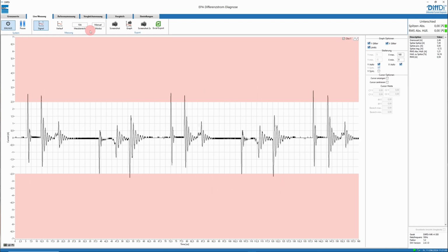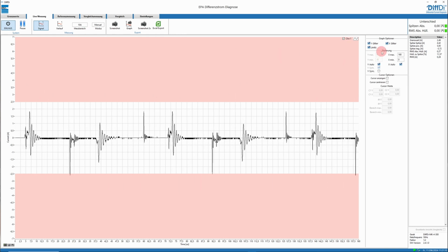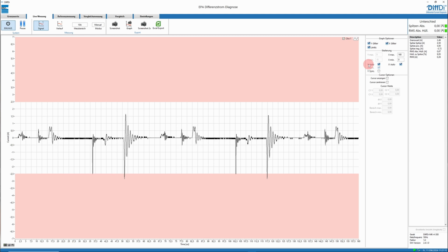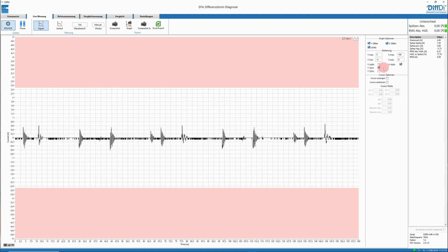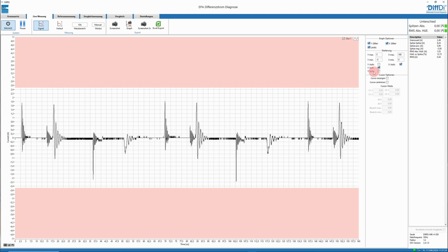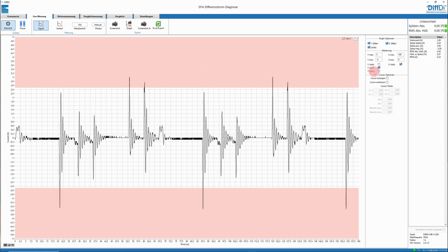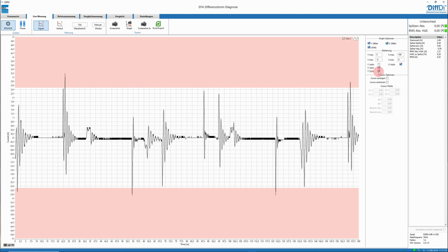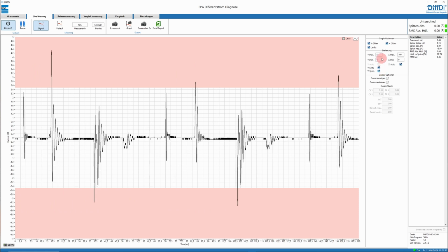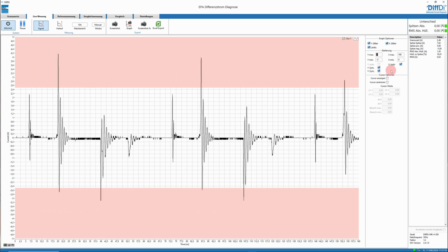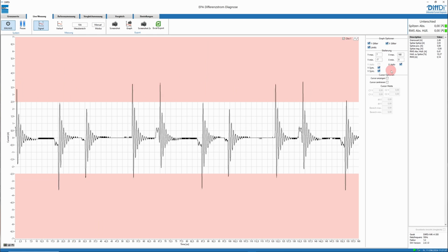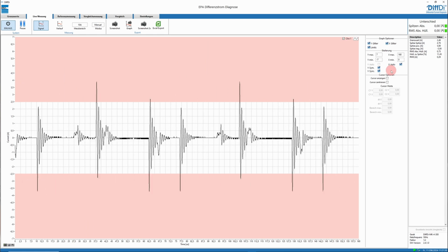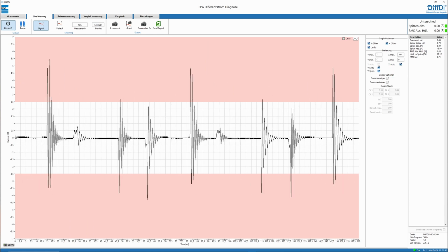The scaling of the 2 axes is normally set to Auto. Manual entry of the scaling is also possible under the graph options and, as in our example, also makes sense. Before entering a value, you should check whether the Y-sync checkbox is ticked. This has the effect that the value entered for Y scaling is transferred directly to the following measurements and the result is therefore more comparable.